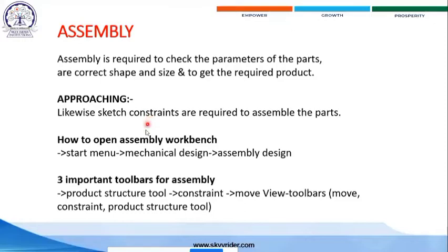Next, we should know how to enter into the sketch and how to enter into the part product. Just remember this. Then I will show you in the software how to enter into the assembly workbench. First of all, we have to go to the start menu, mechanical design, then assembly design.